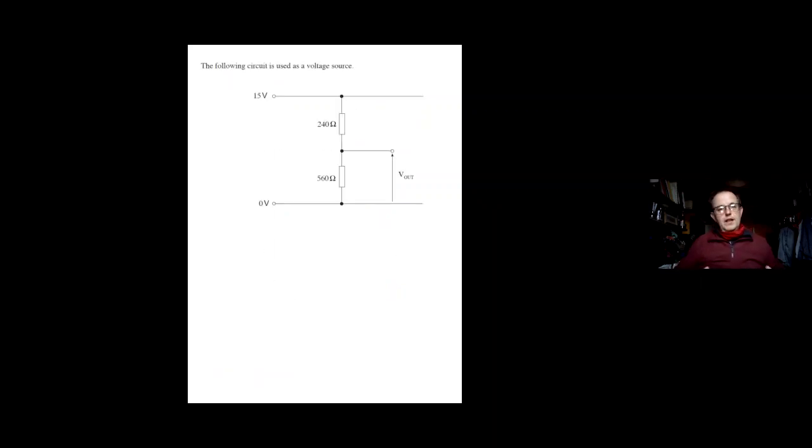And away we go. Now then, first thing about transistors and MOSFETs, they will commonly be connected to a potential divider. A potential divider is basically two resistors. Often you will have a sensor of some kind. For example, that could be a thermistor, or it could be a light-dependent resistor, which will change the voltage which goes into your transistor.